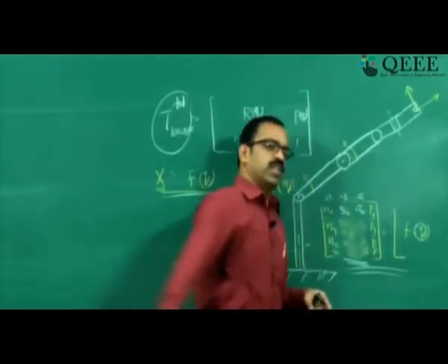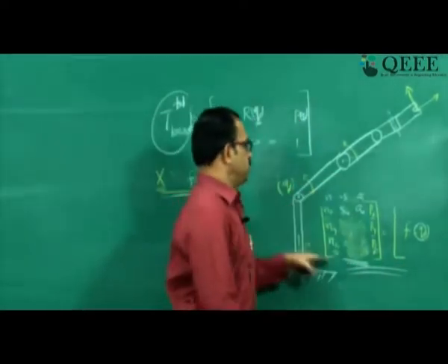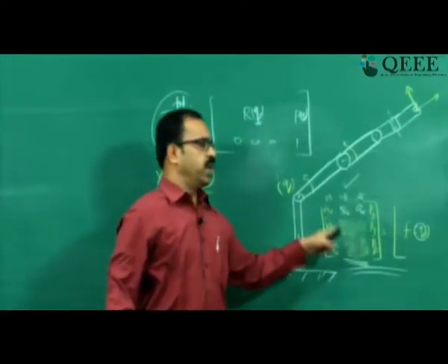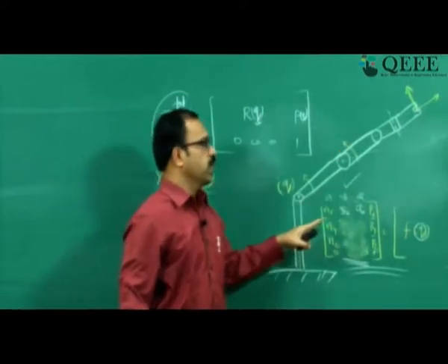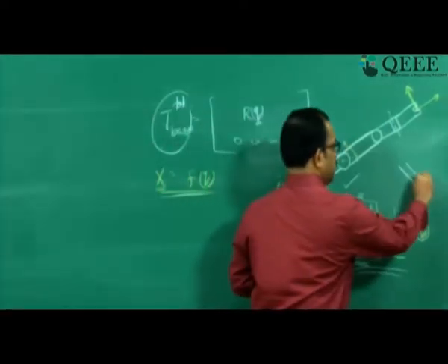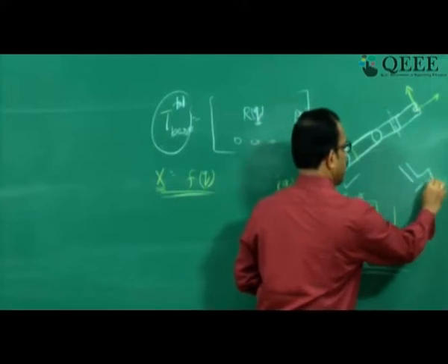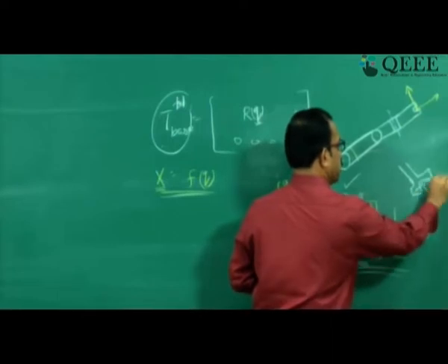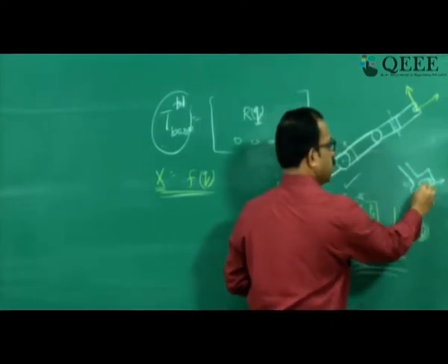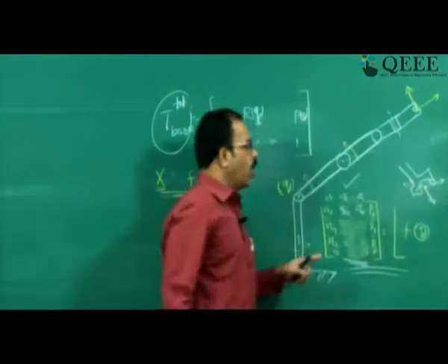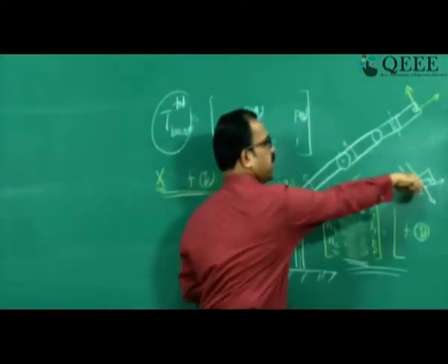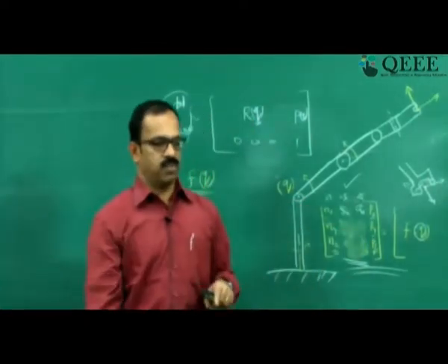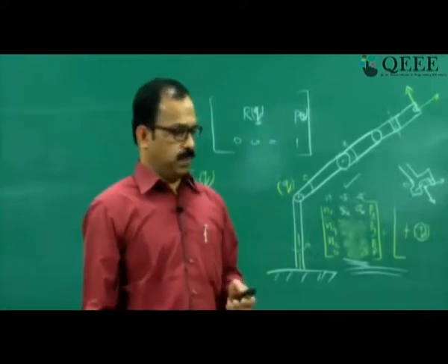So the inverse kinematics problem is that if the position and orientation of the tool tip is given to you, suppose this is the orientation needed for the tool tip and this is known, how can I find out the joint angles to reach this position and orientation? Finding those joint angles, the joint variables, is the inverse kinematics problem.